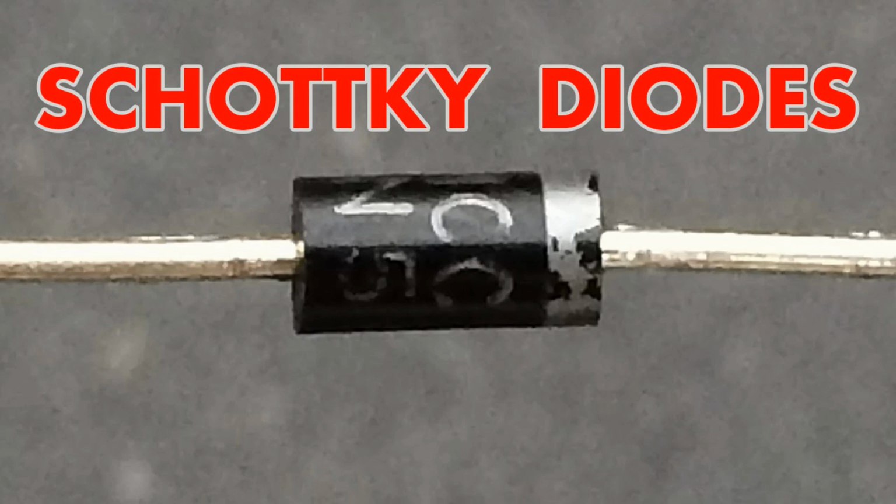Schottky diodes. Schottky diodes are used in high-frequency applications and situations where fast switching is required due to their low forward voltage drop and fast reverse recovery time. Fast recovery diodes. These diodes are designed to have a reduced reverse recovery time, making them suitable for high-frequency and fast switching applications. Ultra-fast rectifiers.